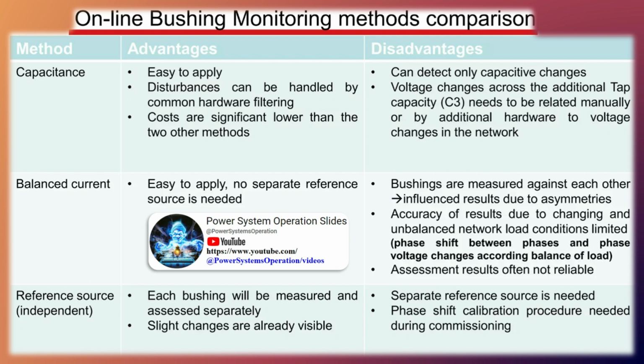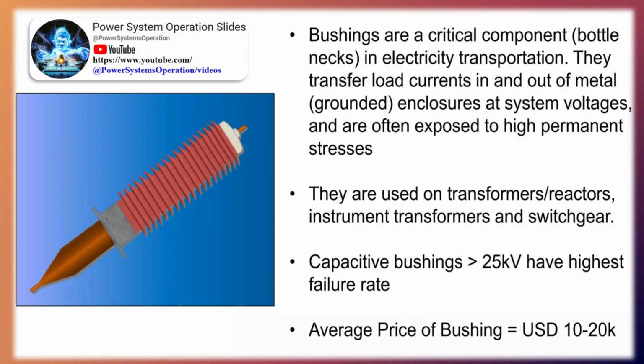Online bushing monitoring systems have been successfully used by the utility industry for over 20 years. They have a proven track record for being able to identify degrading bushings early in the failure process. By providing early warning, users have additional time to plan and schedule an outage to replace the bushings. While there are many users that have successful online bushing monitoring programs, some users cite problems with false alarms from the monitor. While there can be multiple reasons for a false alarm, sensor-related problems are one of the more common complaints. The use of properly designed sensors and correctly installing the sensors can improve the reliability of the online monitoring system.